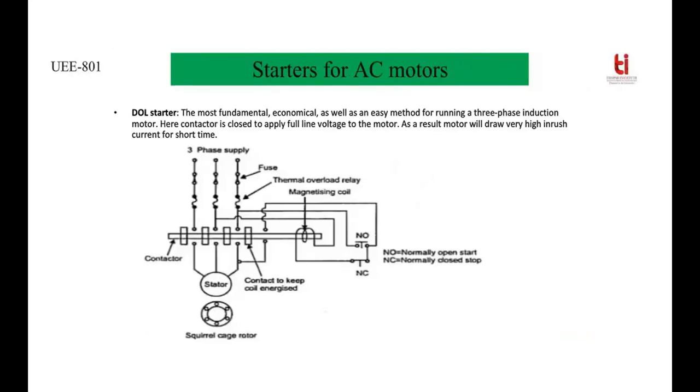Starters of AC motors. Let us discuss the direct online starter in brief. It is the most fundamental, economical as well as easy method for running a three-phase induction motor. Contactors are used to connect the three-phase supply with the three-phase stator windings. You can see the fuse and thermal overload relay. These are used for short circuit as well as overload protection. So these are separate issues or separate problems to solve. But contactors here are used just to provide a path from the three-phase supply to the three-phase stator side.